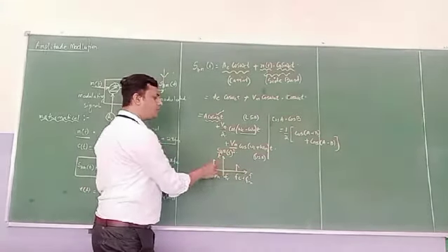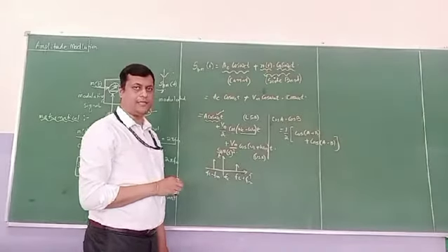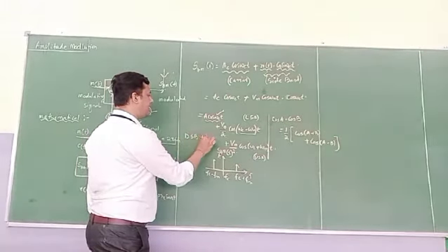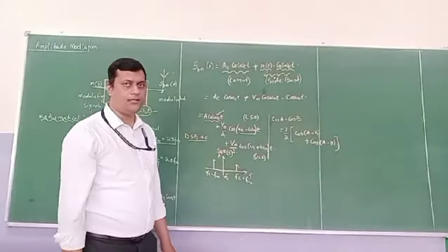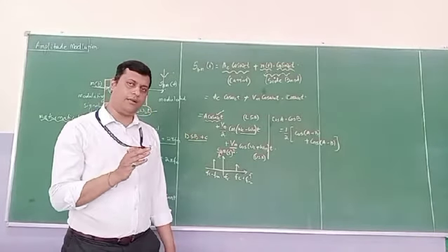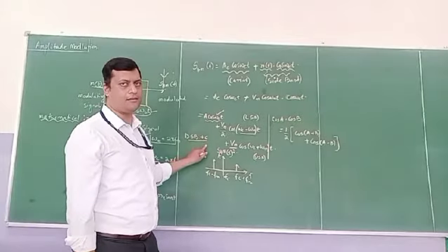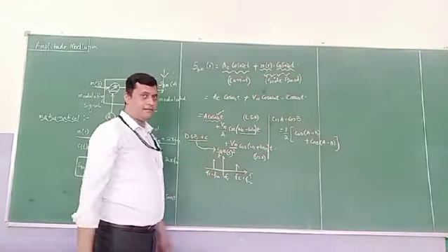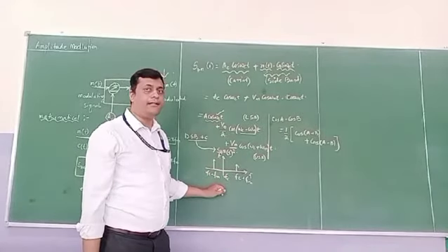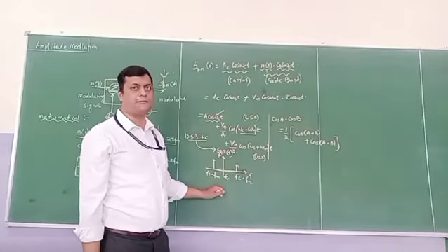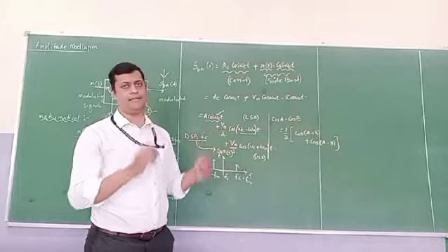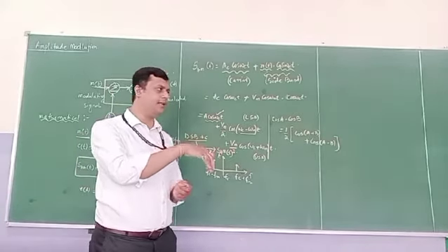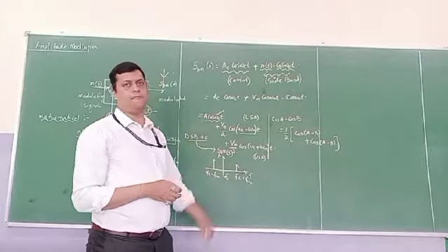So these are the two sidebands with one carrier component, and this is called double sideband with carrier, DSB plus C. Your AM signal is also called double sideband plus carrier component. So here I am representing the frequency spectrum. Always remember this: spectrum means a band of frequency, a representation of a time domain signal in a certain frequency domain, and it will be represented in a certain bandwidth.